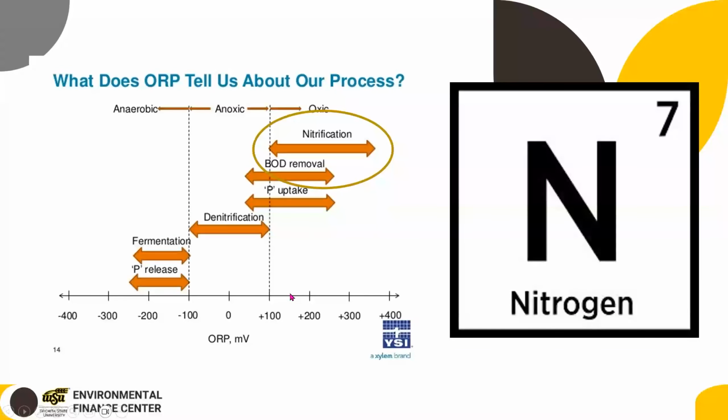And then once the ammonia is basically gone and you've created nitrate, still a source of nitrogen, it's still a soluble source of nitrogen. To get rid of the nitrate that you just created, you have a low oxygen environment. I like a target of -100 at least to begin with, and then you refine that target based on your experience. And so that'd be a fairly high BOD and low oxygen environment.